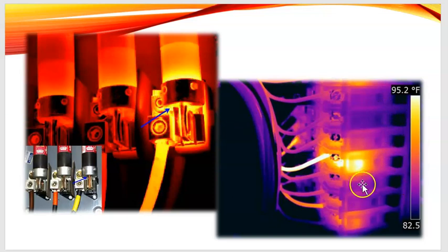You could also look at this, which is a 120 volt, probably a 120, low voltage wire transmitter, and you notice that this particular connection has some pretty good heat coming out of it. So is the thermal or the overload for that breaker happening at this time, or disconnect if it's not a breaker. But again, you can look at it and say, okay, wait a minute, our camera is reading white at 95 degrees Fahrenheit. Well, that may not be too bad for an electrical connection, and it might be that this one is generating a fairly good load. This one may put some load, and the others may be totally off, nothing being generated. Nothing being used downstream on the power. So always keep in mind that the temperature of what you're looking at may be a factor in whether it's something you need to act on or not.